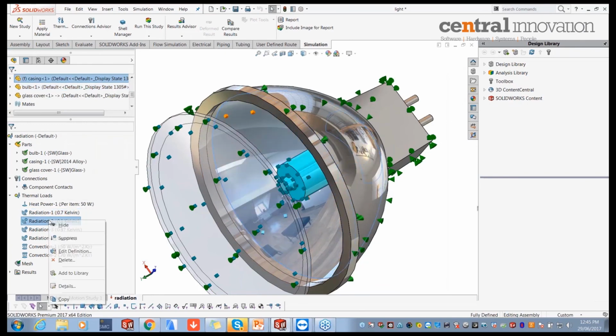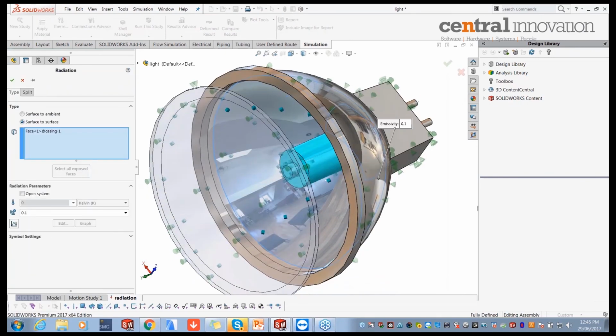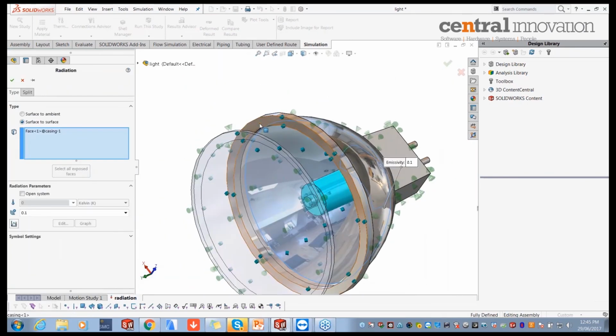The next is the reflector. The reflector is supposed to reflect out the majority of the radiation it receives. That's the purpose of it. So it has a shiny surface and it's made of aluminum. So what I'm going to type in here is a value which is closer to 0, which is closer to a perfect reflector. So that's typed in as well.